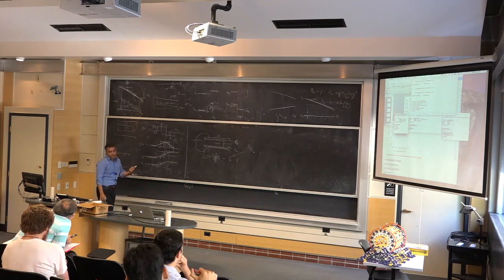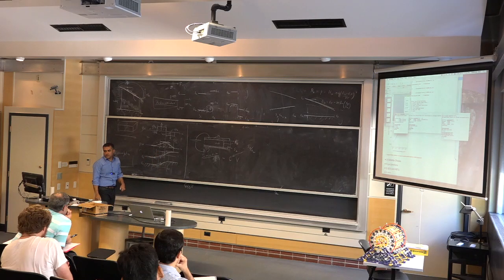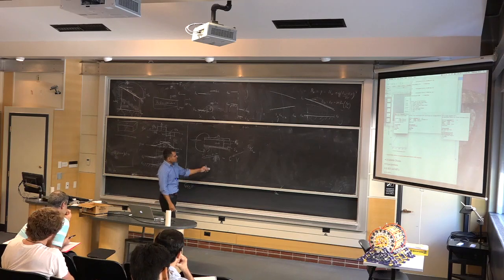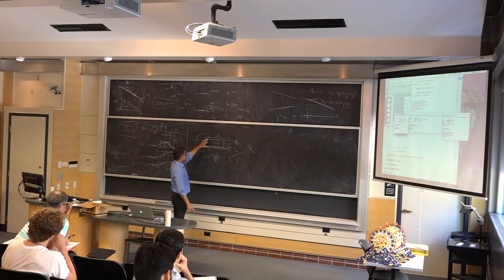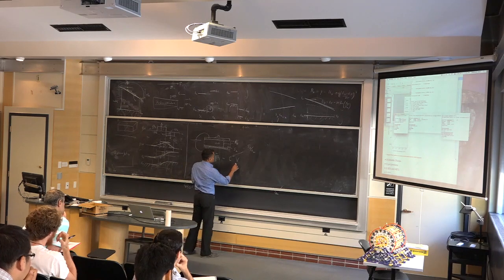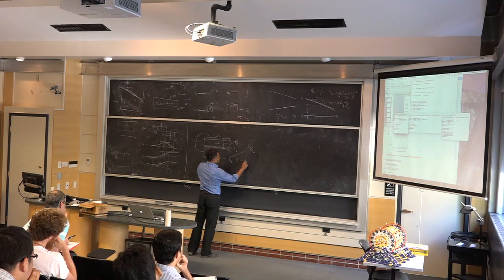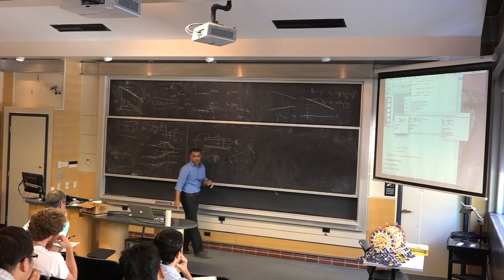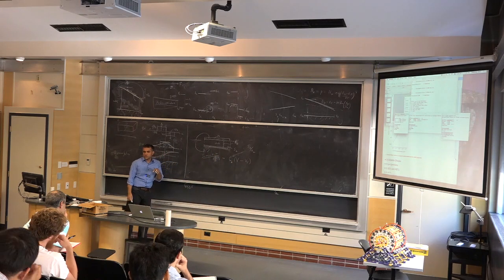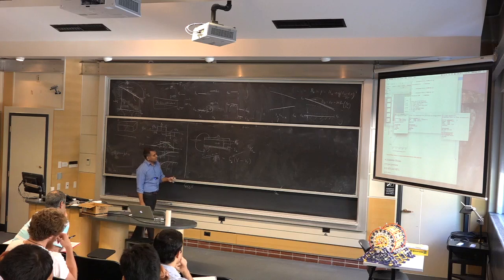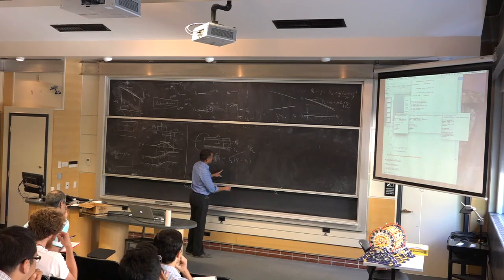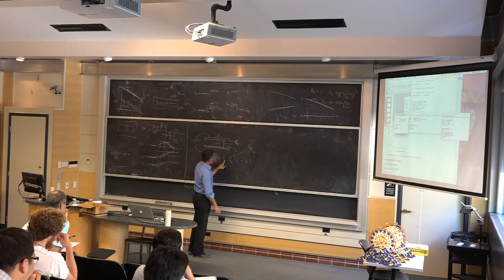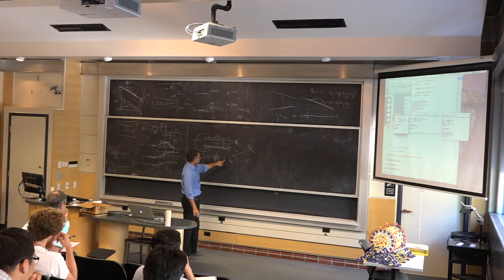So now the question is, what is the charge as a function of voltage? And so the answer will not be very different. In fact, in a semiconductor, they will typically have a work function and all those other things. There's a little difference. And you can write now that, let's call this CB, it will be V minus maybe some threshold voltage, which is required to put charges in the semiconductor. This is what we generally use. And what we'll see in the next class is this is kind of correct, but it's actually not quite. There's a lot more complexity to this. And that's kind of the heart of many of these devices we are going to look at.